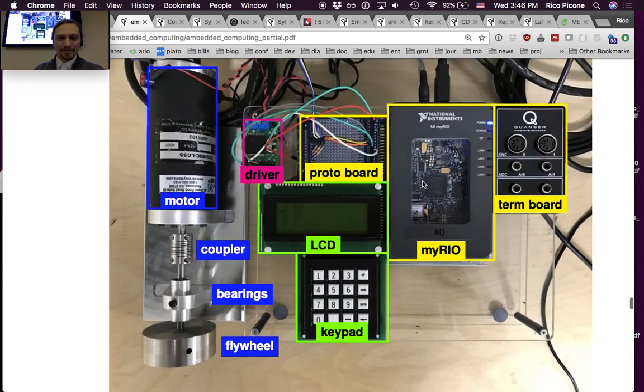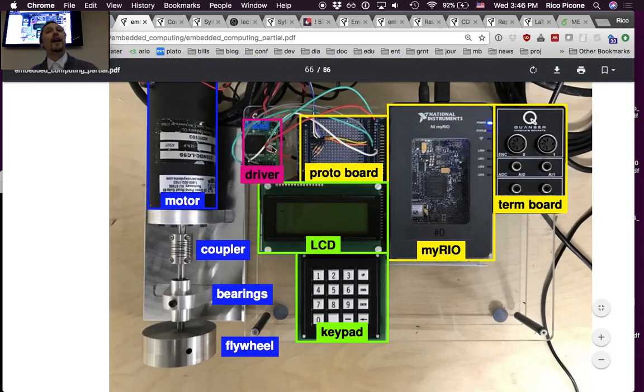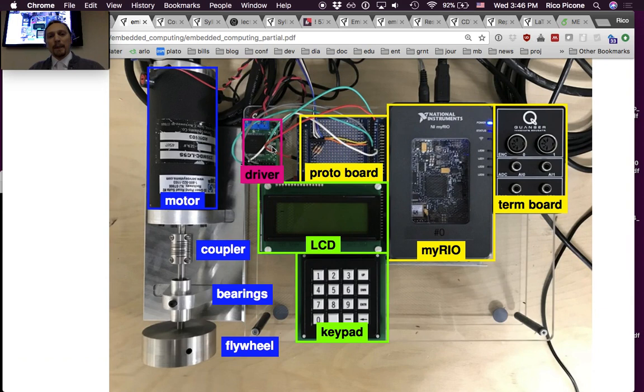Okay. So for the driver, does it come with the DC motor? The driver is purchased separately, and I'll discuss how we would go about choosing that later on in the course. But what it is, it's a microcontroller of its own, and then there's some circuitry on there. So it's like an H-bridge circuit. We'll talk about that. It allows you to drive the motor in multiple directions. And it has some protections because a motor is called an inductive load.